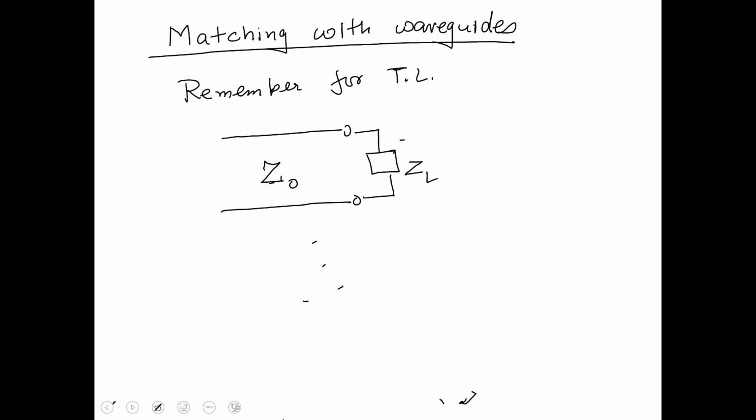Most of the sources have a power amplifier right at the end, and if there is any reflection going back into the power amplifier, you are basically either going to create a resonator or you're going to blow that power amplifier off. So any high frequency sources are very, very sensitive to any reflections you may get within the waveguide